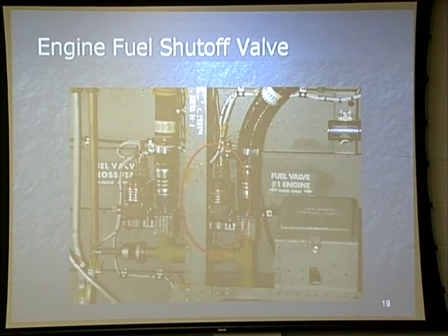Now, the engine fuel shutoff valves. Electrically operated via what? Fire pull handle. Everybody thinks that's a trick question, but it's not. The other thing about it is where does this come in for pre-flight value? In your checklist, it tells you that you're looking for one to be open and one to be closed.